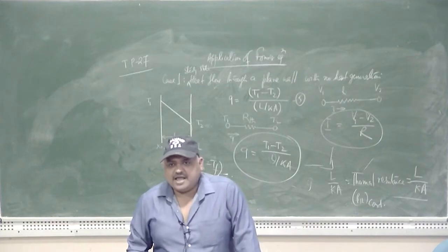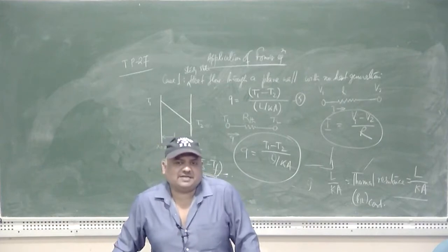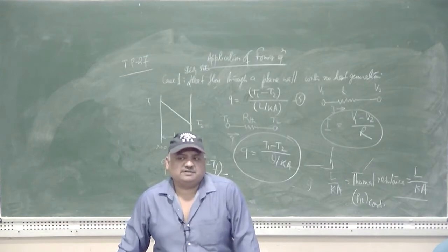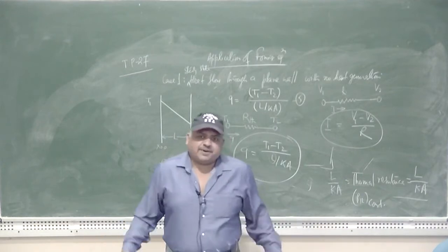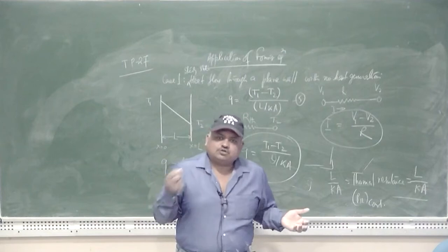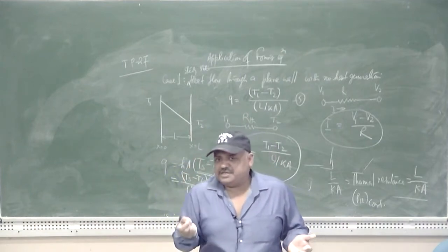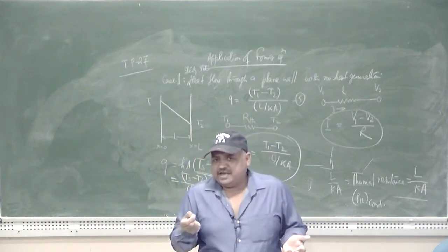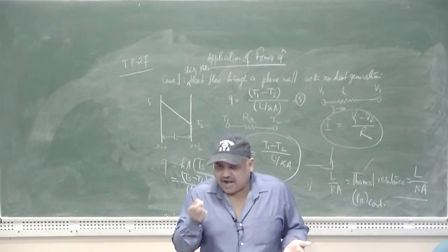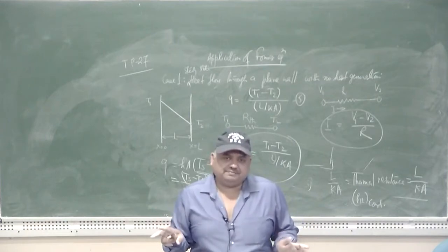Here I have assumed the two types of thermal resistances, that is the conductive resistance as well as the convective resistance. So many times as furnace operates in the air, in the open air it operates. So the concept of convective resistance is of immense importance so far as the designing regarding the thickness of the different refractory linings are concerned.